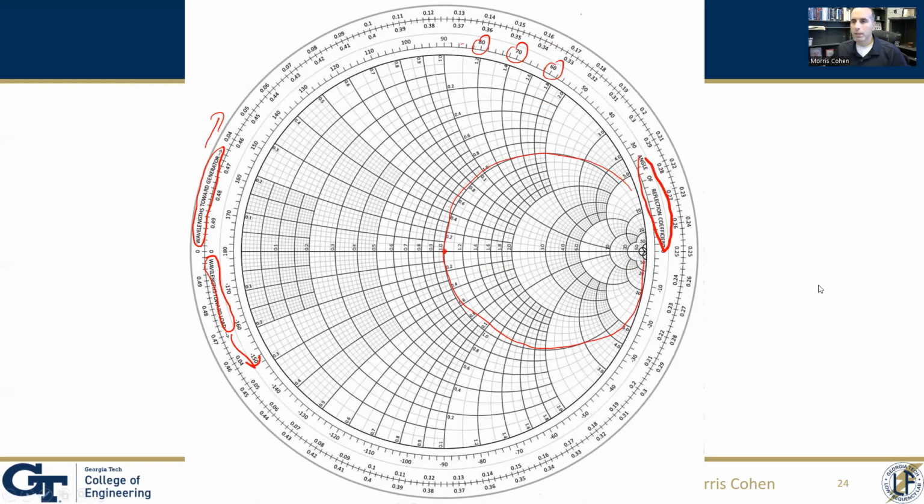So that's going to conclude this video, where we can see qualitatively and quantitatively how the input impedance varies as a function of transmission line length and as a function of what your load impedance is. And so in the last part, we're going to consider impedance matching, or how we actually design transmission lines to minimize reflections back to your source.